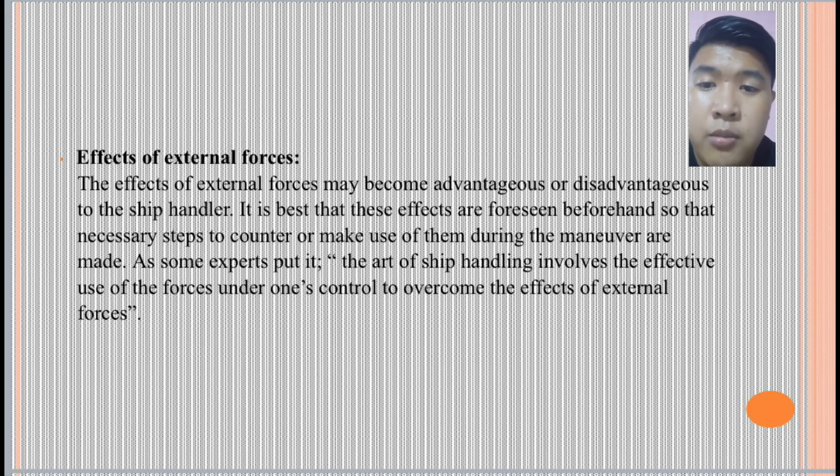This is caused by human factors because the individual you are ordering may have different responses depending on their training and ability to perform the job, or the order has to be relayed by an officer to the helmsman, which is bad practice that should be avoided. The conning officer should be able to give his order directly to the helmsman.